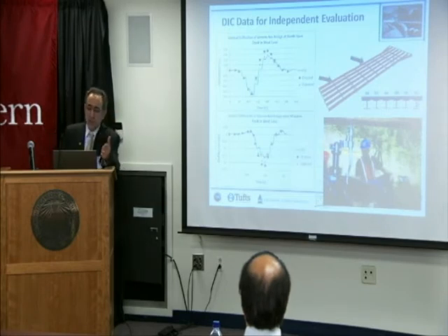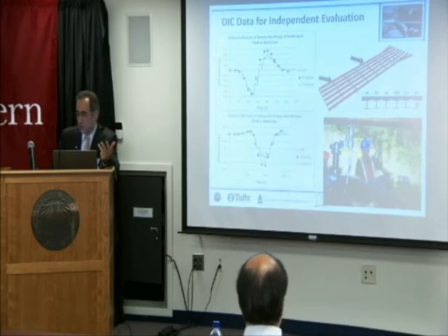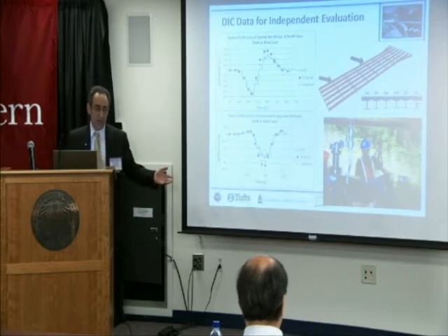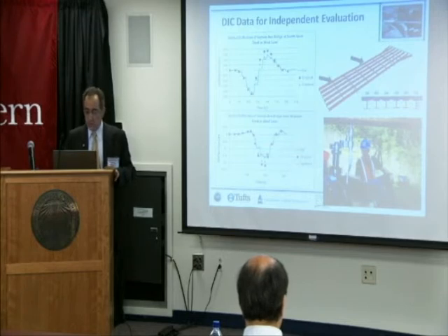Something about instrumentation. I very much enjoy working with strain gauges and tilt meters and accelerometers because they're reference independent. In the lab, you can use LVDTs or RVDTs for displacement measurements, but they need a reference point, and it is very difficult to do that even for a small bridge like this. And we need to have high resolution measurements.